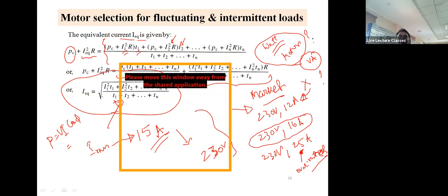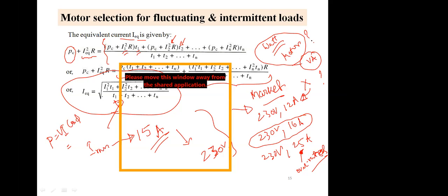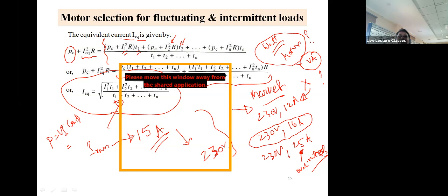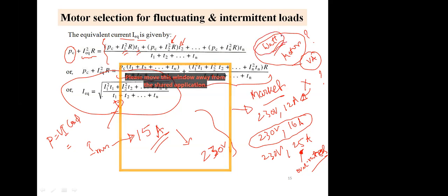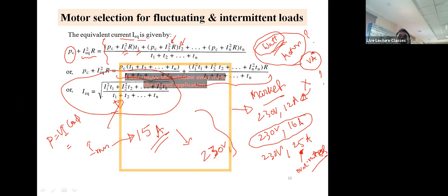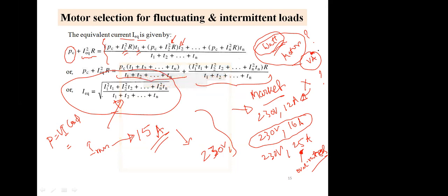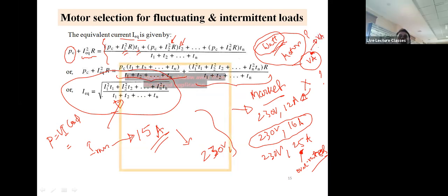The rating depends upon the type of output you want. A motor will give you a physical rotational output, that's a mechanical output which is real, so real is watts. And electrical output is given by a transformer, so its voltage and ampere consist of the real power and the reactive power also. So it is in VA.